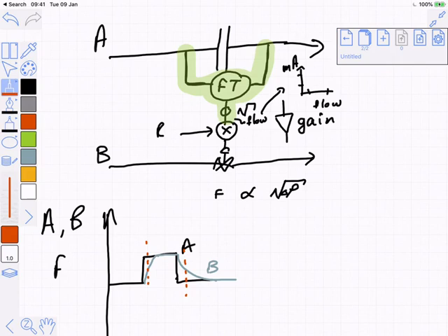So what's the final word? How do I know what conversion I'm getting? I measure the conversion. I measure the actual stuff coming out of my reactor. And if I'm not getting the conversion that I wanted, I make changes to the operating conditions on the site. And how do I do that? By using feedback control, by measuring that thing and saying, well, if the conversion is too low, I must increase the amount of the limiting reagent that I feed.